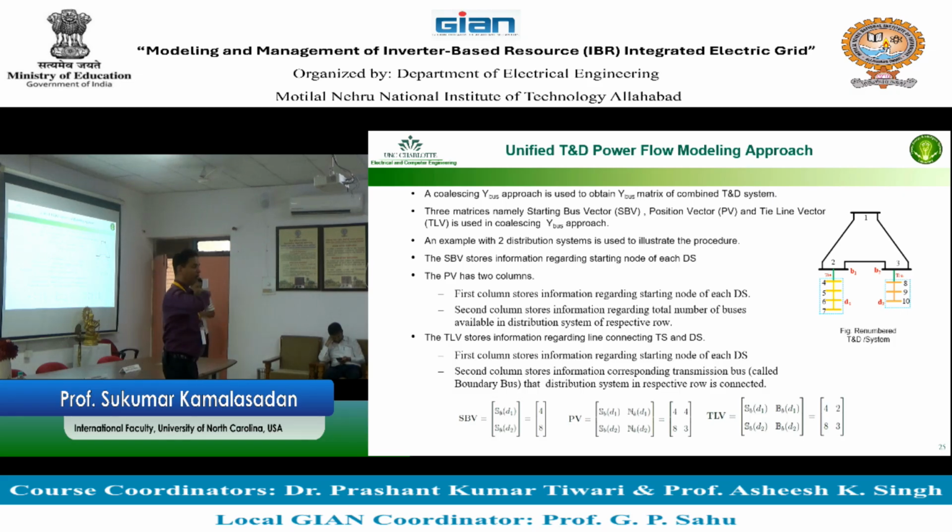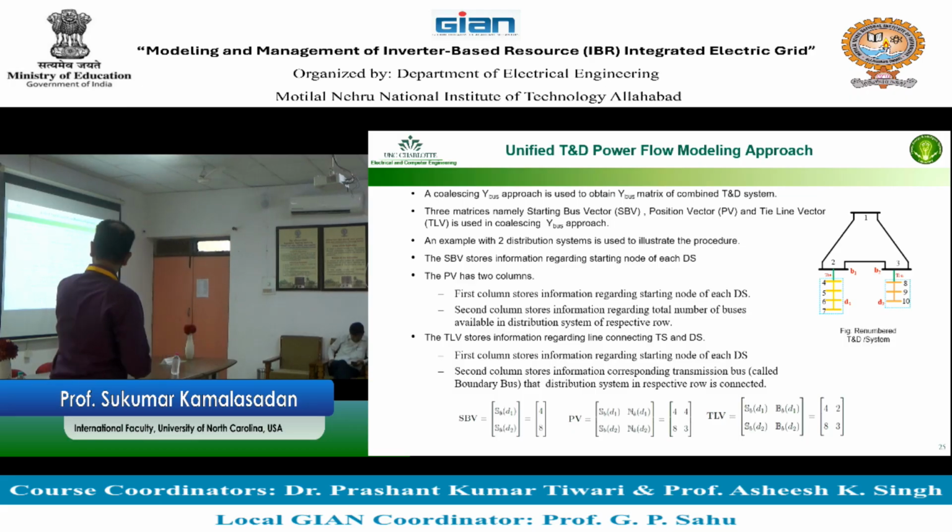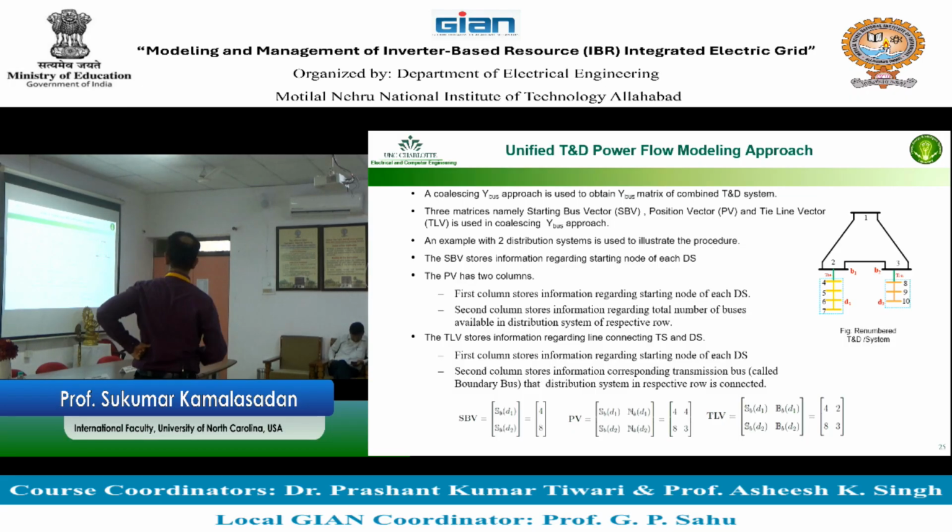And why do you want to run this? Oh, now the next question, that's counter thinking, right? Why do you want to run this power flow? I already maintained that voltage properly. I know it's 1.05. Well, if it is 1.05 and with that load, is that whole integrated system stable or not? That is something that we are testing. Especially with DERs, because otherwise it's mostly stable. Does that make sense? That is the idea here. So once we develop this,